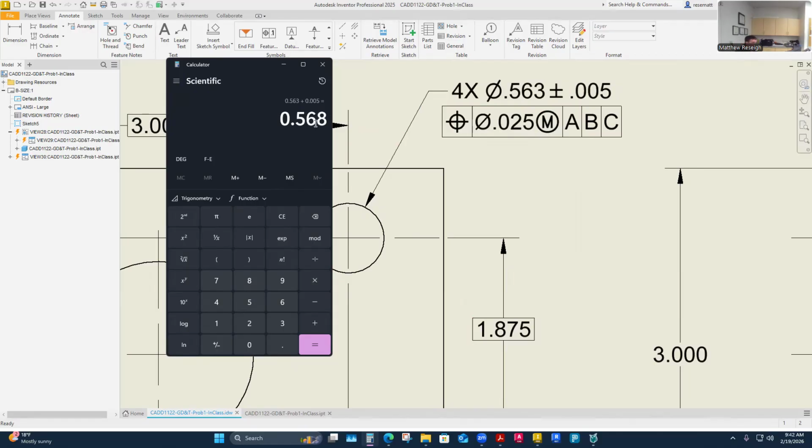Back up. Well, maybe this works. I don't know. Does it work? Roll with it. What I'm saying is that would be least material condition, right? And so if my part size is this big, how much positional tolerance am I allowed here? So this would say at maximum material condition, you're allowed 0.25.